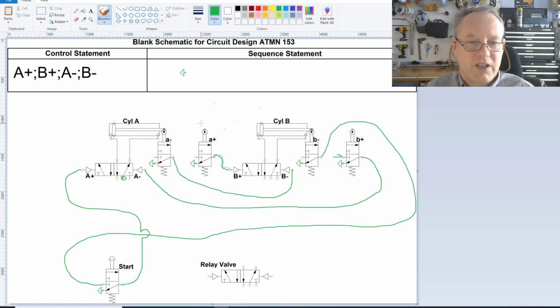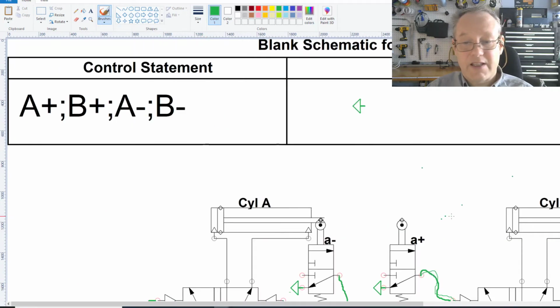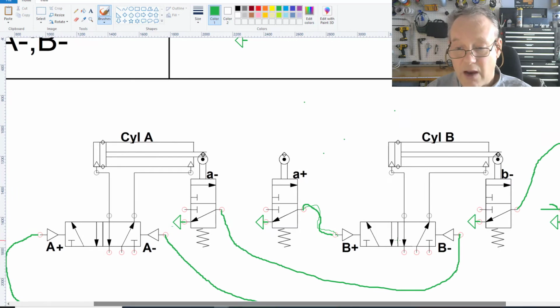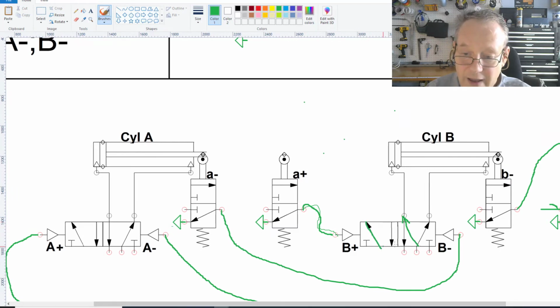You couldn't physically push it back because there's pressurized air going up here. Even though it's extended all the way, that pressurized air is still there. So what's next is that when this gets pressed down, air comes out of here, it goes into here, it shuffles this valve over. This valve now is sending air out here, because this guy is now over here, and because this guy is in between here and here, the air coming out of here will do the same thing. So